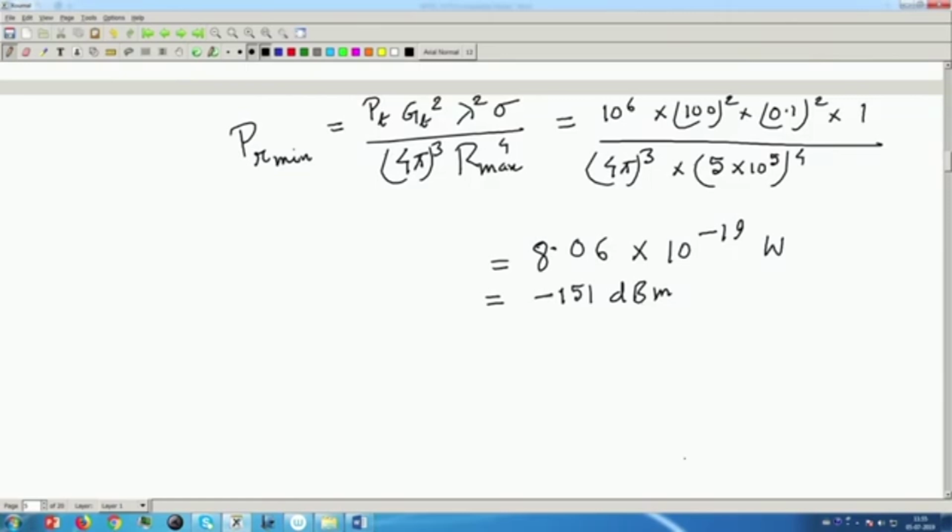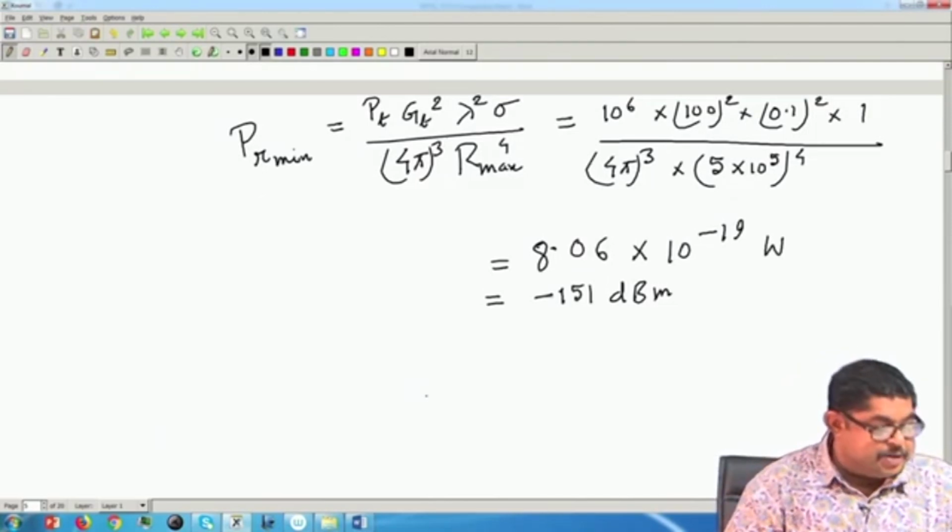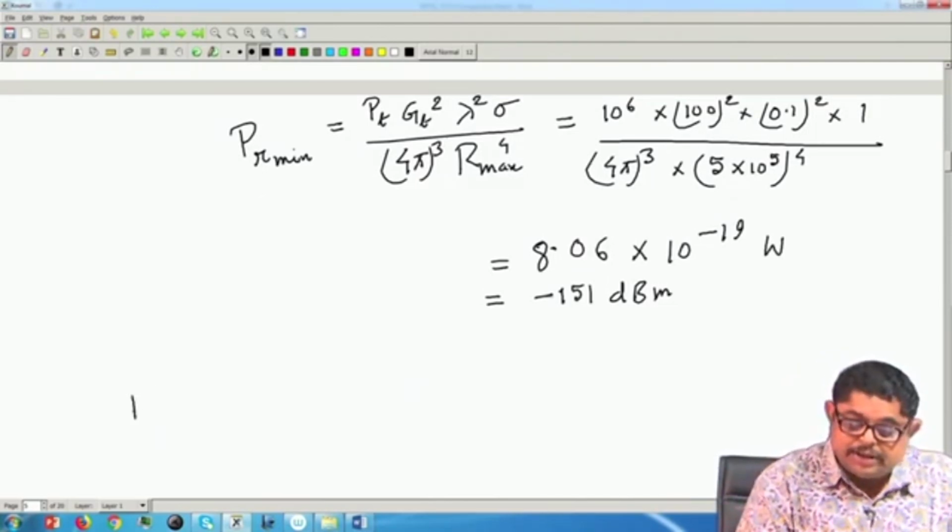Okay. So, first part is the receiver sensitivity, we got that; this is the minimum that will come. Then find the minimum number of echo pulses required to be integrated by the indicator for detection of a point target. Now, detector sensitivity is given as minus 141 dBm, whereas receiver sensitivity is this. So, that means by integration we will make up this 10 dB.